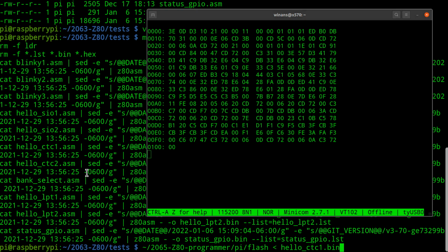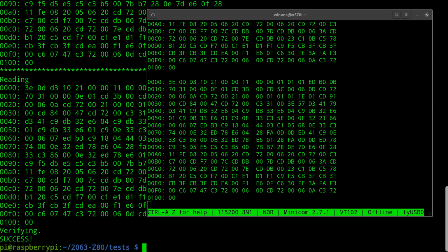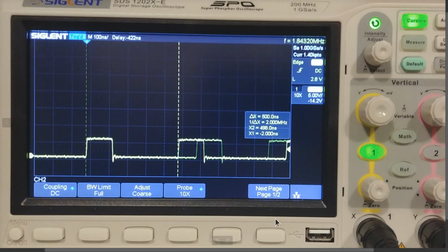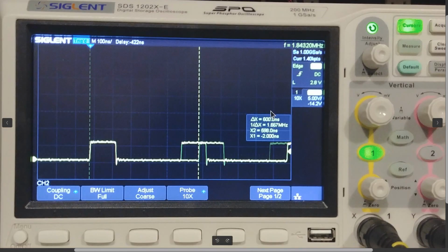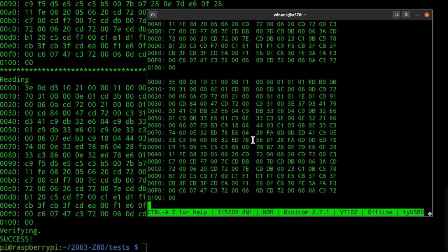Hit enter, and let's see what happens with on the order of 20% of jitter. Will it work? I think the answer is yes. It does work, okay? We got a 20% jitter, and we're still flying. Let's look at the oscilloscope and have a look-see at just how bad this really is. And keep in mind, this is jitter, not frequency error. And the takeaway here is just how robust RS-232 really is in the face of jitter.